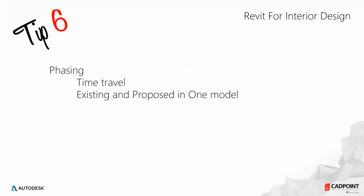It takes a little bit of setup to use it properly, but once set up, you won't know how you work without it. The premise is you become a time traveler. When you're in a view that is existing, you can think of yourself in the past. When you're in a view which is proposed, you can think of yourself in the future. Any objects created in an existing view are existing objects, and any objects created in the proposed view are the new objects.